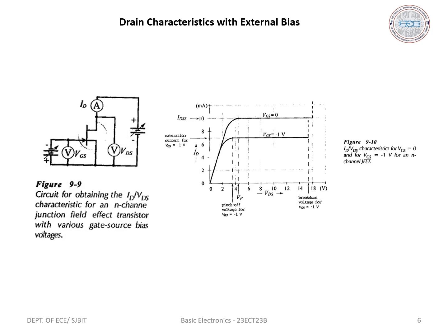That is, a family of drain characteristics can be obtained by using several levels of negative gate source bias voltage. If positive VGS is applied, a high level of ID is produced as shown in the figure. VGS is kept negative to avoid the possibility of forward biasing the gate junctions. The dashed line shows that ID saturates for each level of VGS.